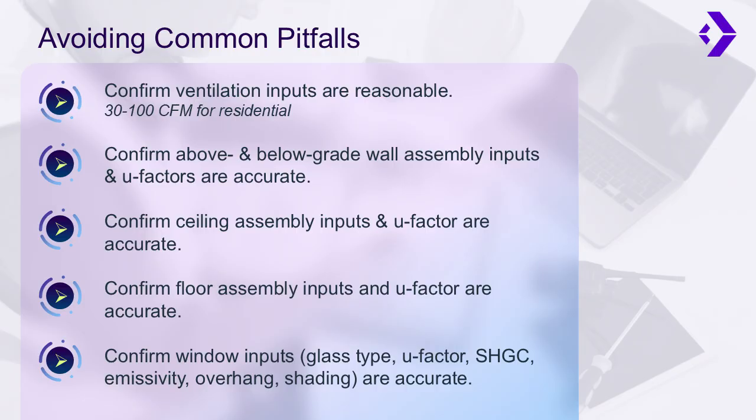According to Standard 62.2-2016, homes should receive 0.35 air changes per hour, but not less than 15 cubic feet of air per minute per person. Homes that meet their air change needs with infiltration through the building shell should have no load for this category. Kitchen, bath, and other ventilation that only runs occasionally should not be included in the ventilation load.